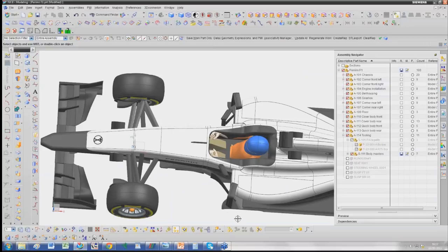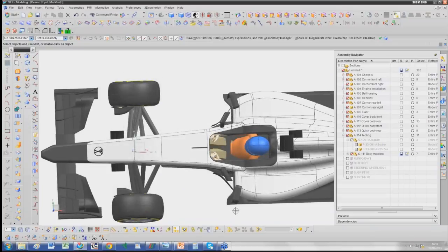The other thing on this simulation is the car is a little bit high in terms of ride height, which means also the front wing is not performing as much as it will on the racetrack. We just need to lower the car a bit, and that will make the whole vortex much stronger as well. So it's all part of the process of just developing the geometry of the car, knowing what we want to do, and we have some, obviously, some targets. The Y250 vortex being stronger is one. And then play with the attitude of the car and just carry on like this.